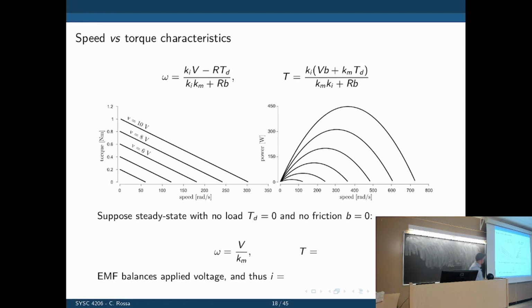But then we see now the operating ranges of the motor. So whenever you buy a DC motor for any purpose, you'll be provided with these charts. And in those charts, we have red and green zones where you can operate for long periods of time, and where you shouldn't do that. You can only operate for a few milliseconds. On the other side there, we have speed and power. And for each line, there is also a different voltage. So the voltage is increasing this way, the voltage is increasing that way.